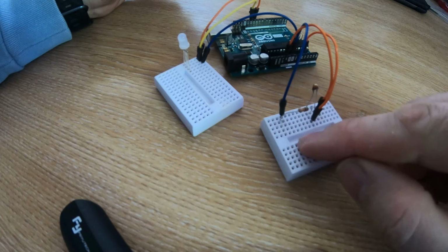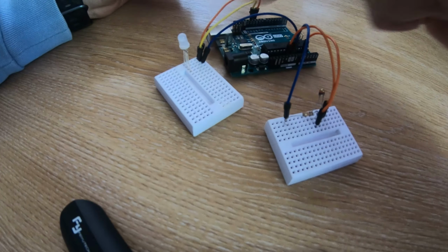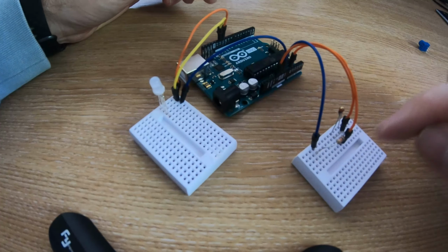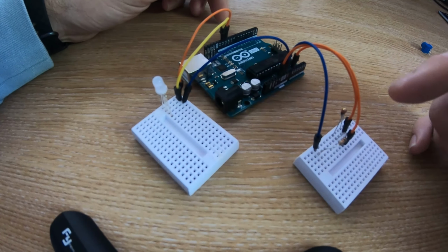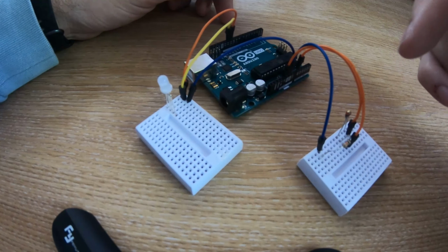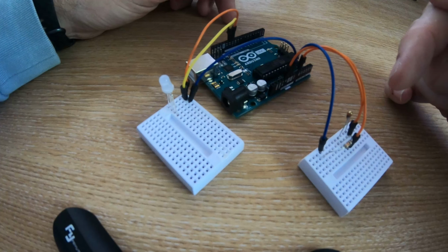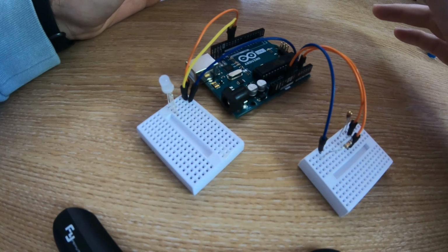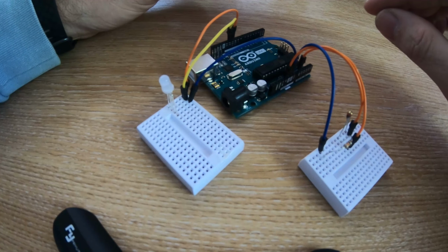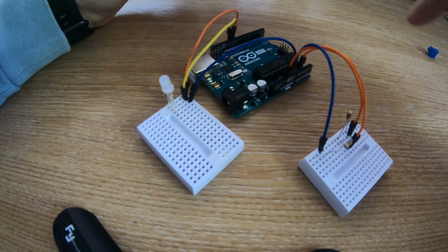So we have our potential divider here feeding into our analog input, and then we have a Tricolor LED as our output. Okay, now we might have a potential divider here, but that potential divider is going across 5 volts. So we've got GND and we've got 5 volts. Now, the way that the Arduino analog input works is it will give you an integer value between 0 and 1023. So across 5 volts, that's 0.049 volts, or 4.9 millivolts per unit.